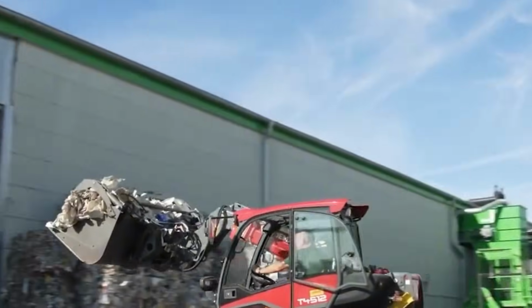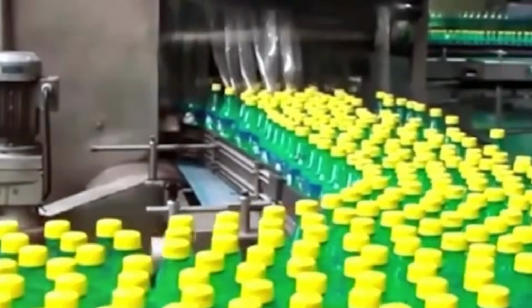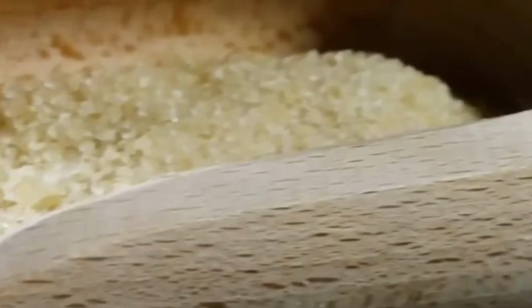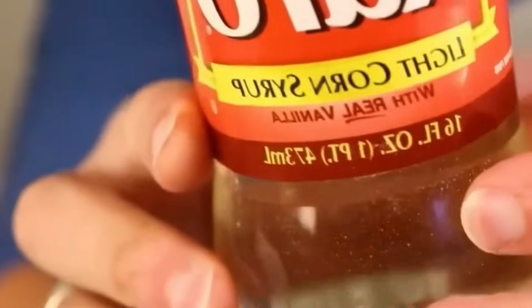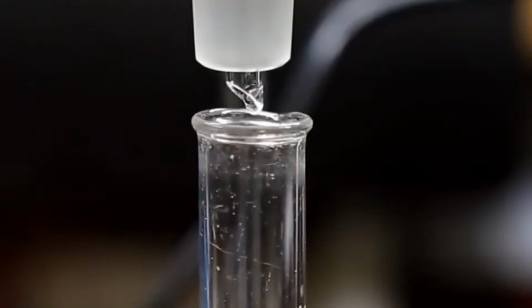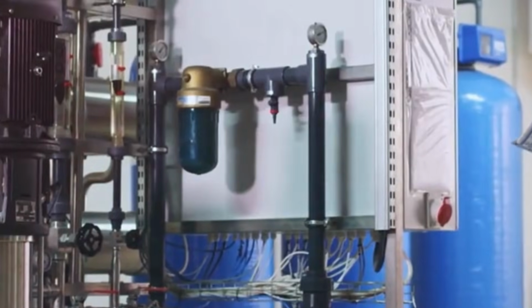For bottles, an inverted air rinse machine uses ionized air jets to dislodge any debris inside. Cans are washed with sterile water sprays and dried with compressed air. Once cleaned, the containers proceed toward the rotary filler. Filling occurs on a multi-head rotary machine where containers are positioned under filling valves arranged in a circular turret.